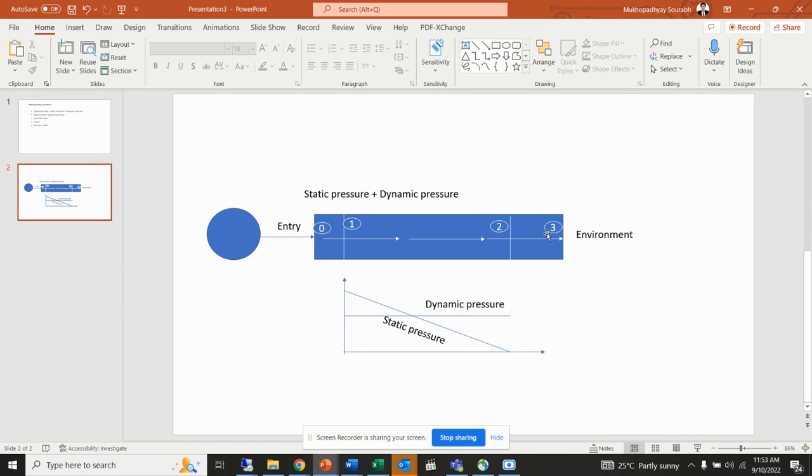But after a certain time, the flow rate will change as well as the pressure will change. So there we will get more thrust as well as more flow. That means we will get both increased pressure and more flow. All those things about pump characteristics I will discuss later. But for the simple case, let's first understand what is static pressure and dynamic pressure. Static pressure is nothing but the system resistance, because environmental pressure is 0. In actuality, if the environmental pressure is something, then static pressure is the system resistance plus environmental pressure.